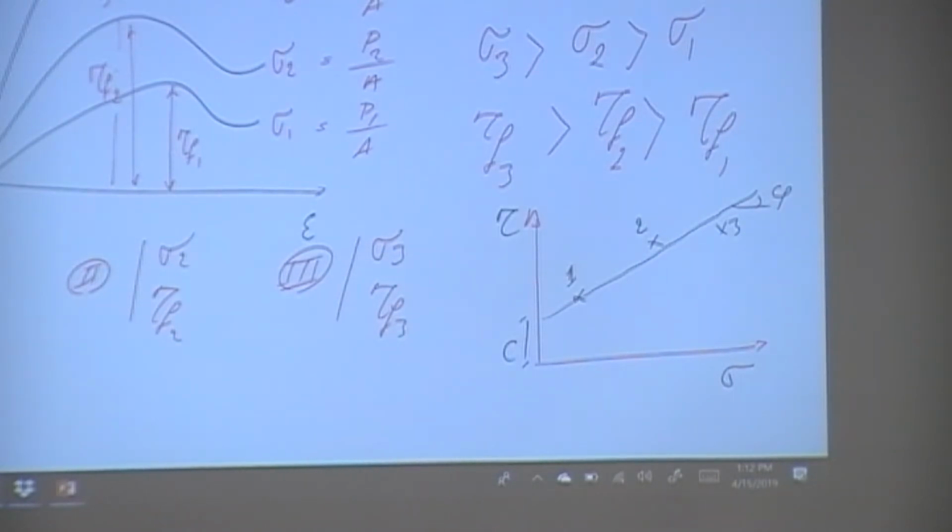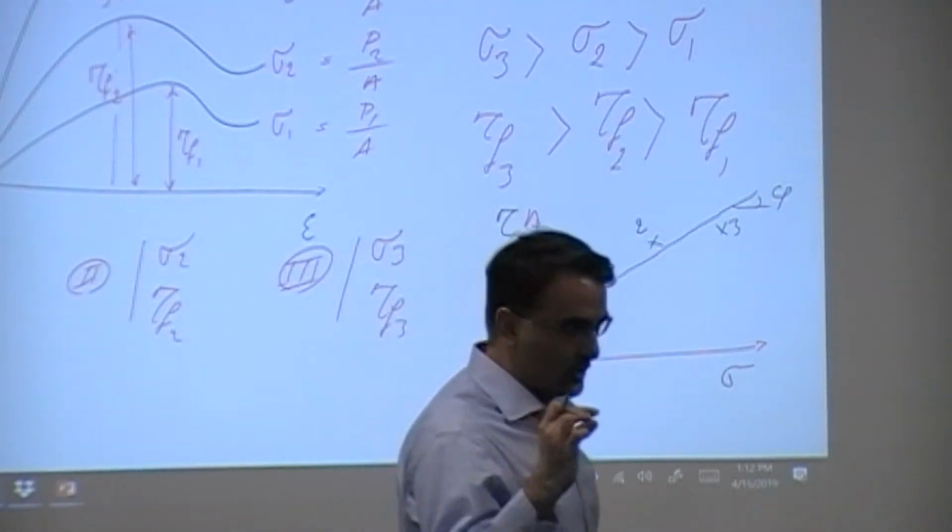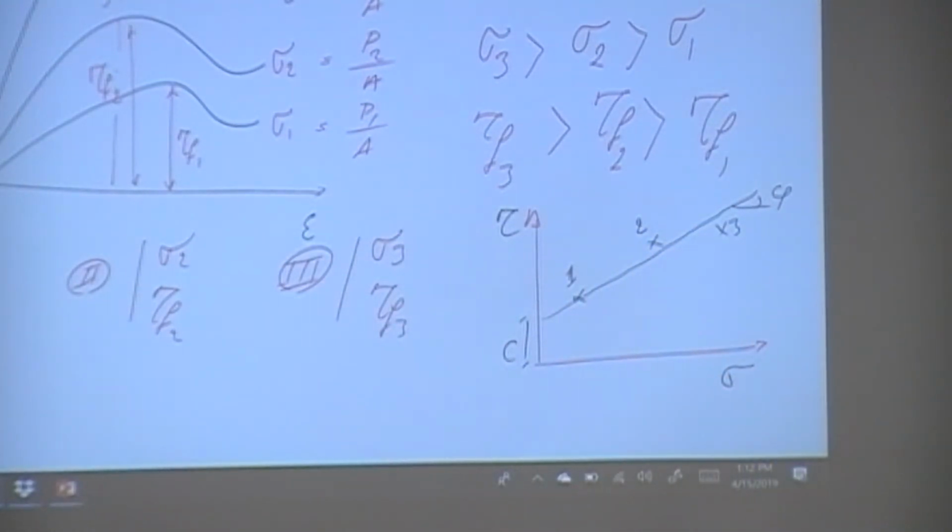The process is we have to run 3 tests, probably with replicates, meaning that you have to run it twice. Each stress is fixed. The first step is to apply the surcharge. We call that applying the confining pressure. The next step is to take the material to failure. Why to failure? Because we are interested in points along the failure envelope. We are not interested in points that are contained below the failure envelope. That doesn't give me the information that I'm looking for.